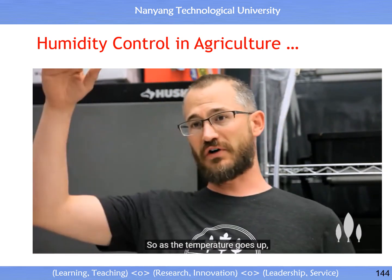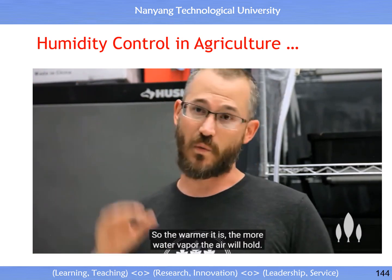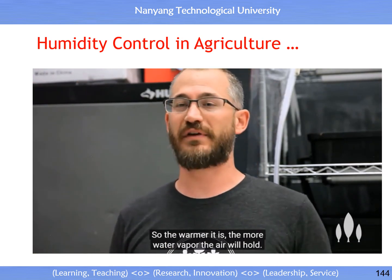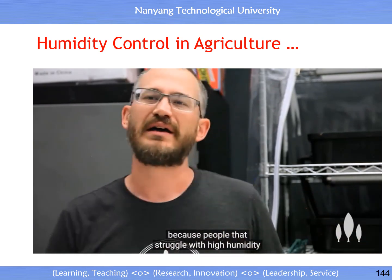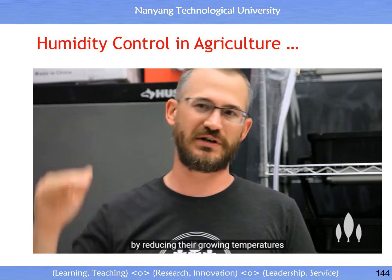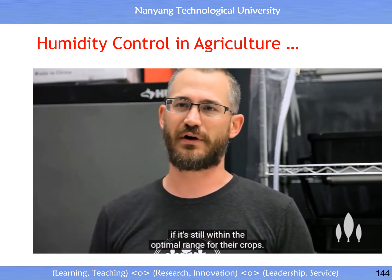Yeah, so when we're talking about environmental controls, it's important to remember that humidity is relative to temperature. So as the temperature goes up, the maximum relative humidity also goes up with it. So the warmer it is, the more water vapor the air will hold. This is really important because people that struggle with high humidity can oftentimes deal with it by reducing their growing temperatures if it's still within the optimal range for their crops.